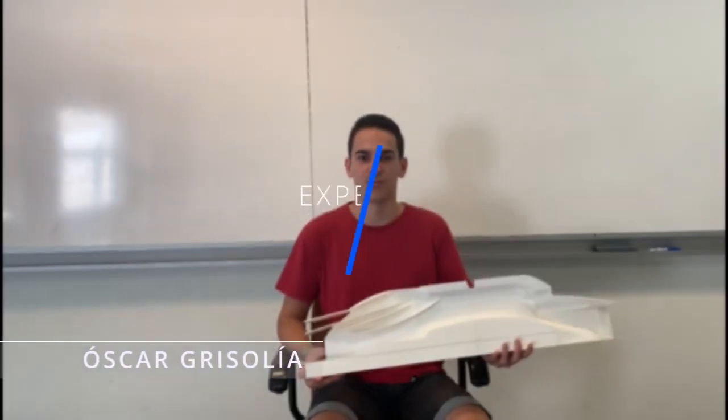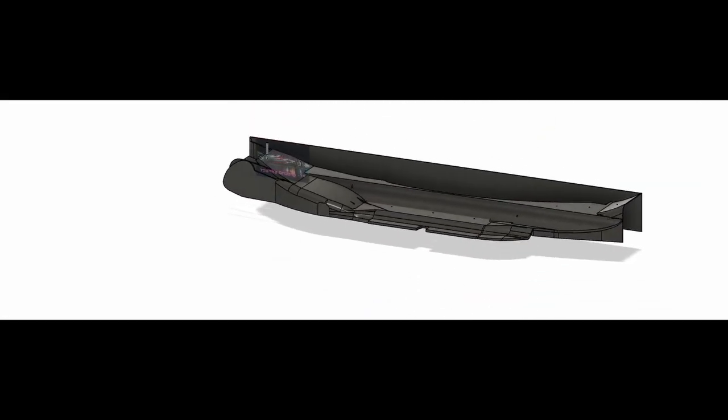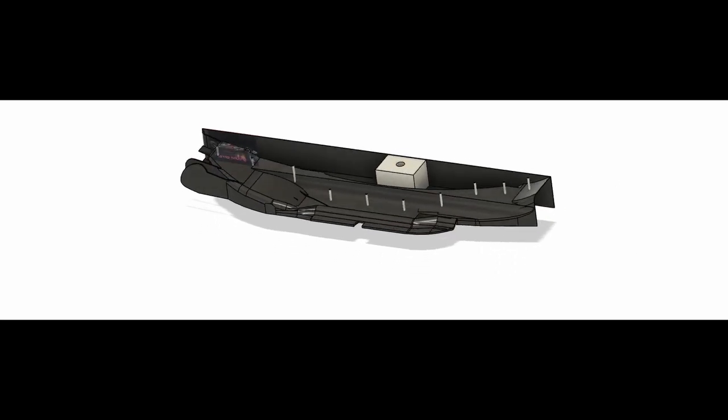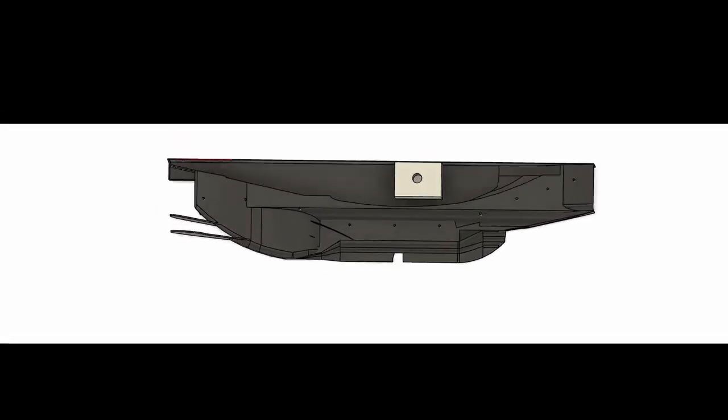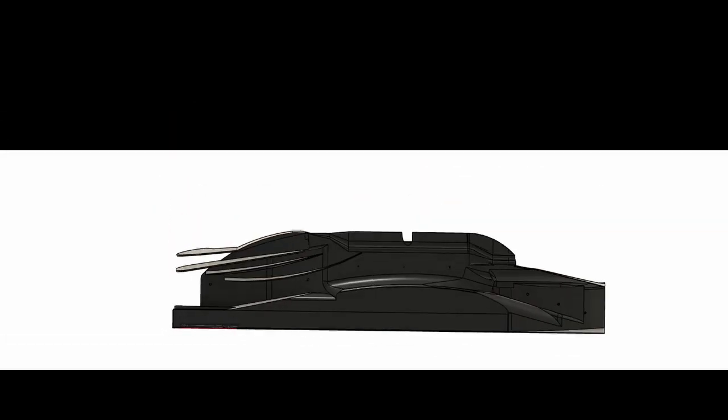In order to put into practice what we mentioned before, we designed this 3D piece. The CAD design of the floor was downloaded from a 3D online repository. Some changes had to be done in order to prepare it for the wind tunnel. It was scaled to 15% of the original size and cut in half. Also, an M6 thread was made so it could be held in the wind tunnel, and finally 16 intakes were added in order to connect the floor to the manometric table. Also, some minor changes in the thickness to improve the quality of the print were done.